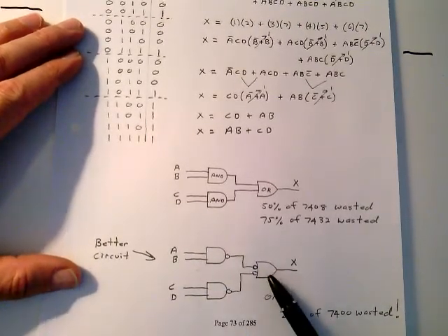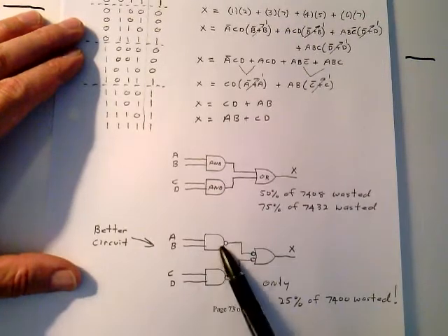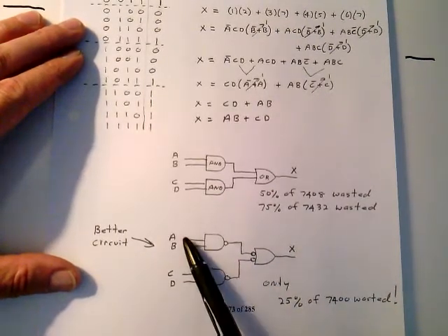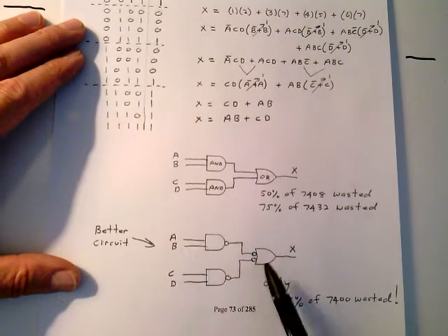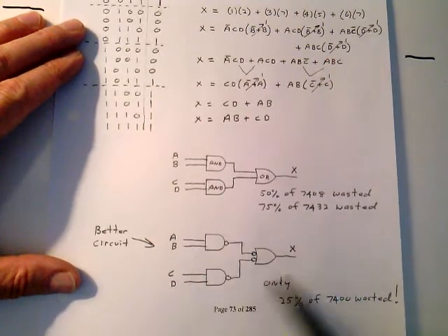And you draw the output NAND gate like this because it's easier to understand when you're troubleshooting it. In your mind, these bubbles can burst. And that output is, if you have a high here and a high here, or you have a high here and a high here, you better get a high there. If you don't, something's not working in that circuit.